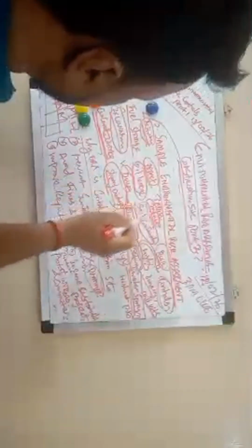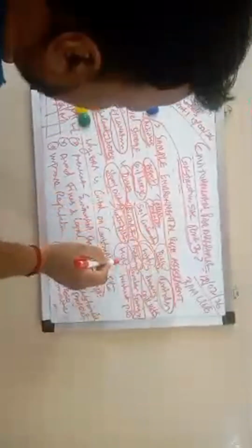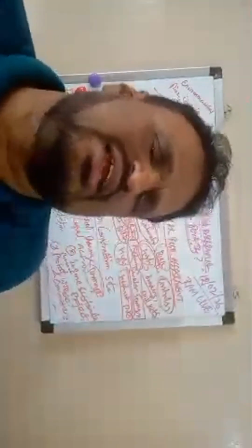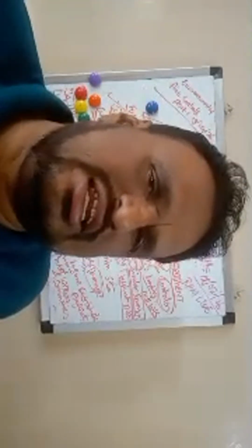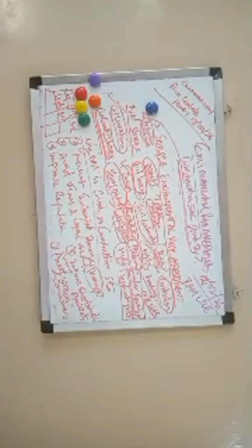Then what will be the impact? Water pollution is the impact. The risk level is high. Then what will be the control? You have to use wash out pits. Using small wash out pits, they collect the waste water and allow sedimentation. So that is one of the control measures.